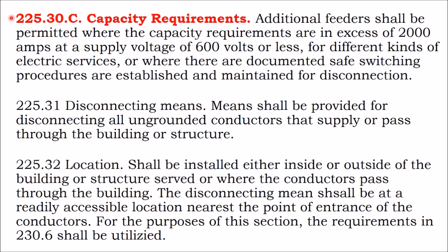In fact, I had a conversation with a solar installer who was trying to research net metering policies. And he said, I have a building and the capacity of the building is huge, but the energy use is really low. And so we want to put all the solar arrays onto this building, but we want to tie the array into the small parking lot meter that is on an energy only rate, because we have 40 other accounts throughout the city that are on energy only rates. And so we want a net meter at the energy only rate, not at the demand charge rate.